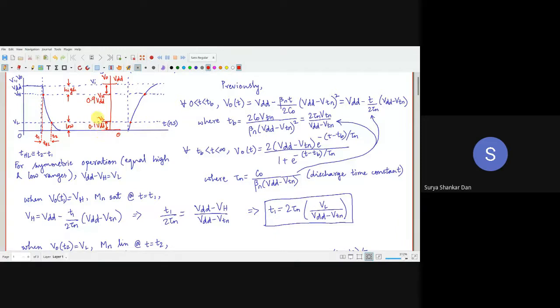Otherwise some of you would do it at 15% and some at 5%. The student who does it at 5% will obviously see smaller rise and fall times. So just to standardize everything, industry has decided on 10%. Please remember, these VH and VL values are something which we engineers have decided. That is the international standard. So VH and VL are 0.1 and 0.9.